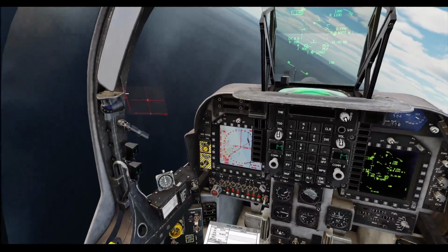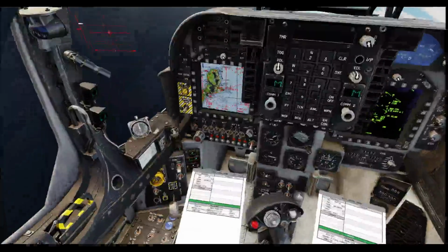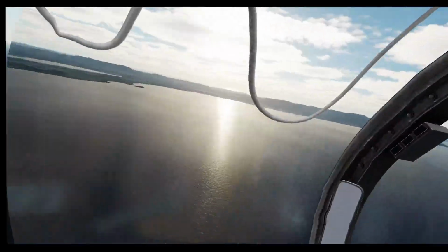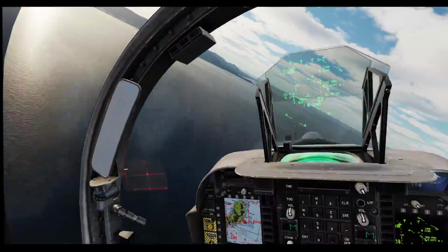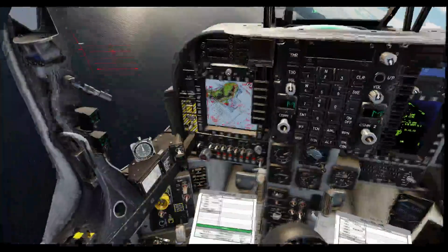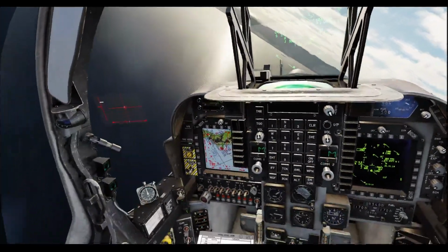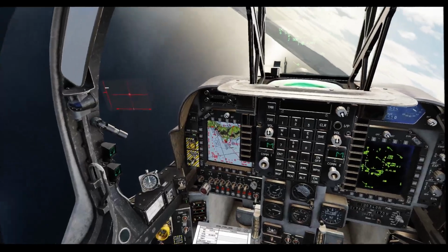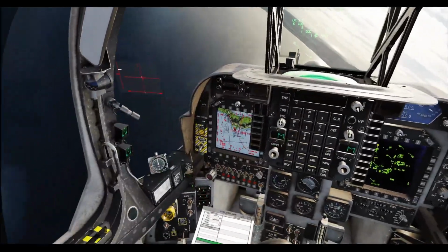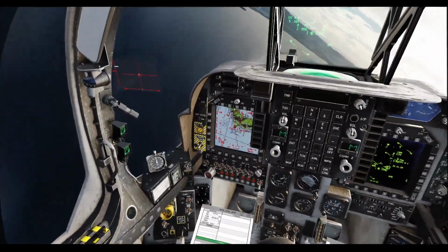And I'm just going to bring the scale out a little bit so that I can see my course line. 0.4, we're halfway through the turn, maintaining that lookout attitude instruments work cycle. So look out the cockpit, reference attitude on the hood, use the instruments to confirm accuracy. So we're at 1.0 miles. 1.2, so we've just got a little bit wide. We want to be between 1.0 and 1.2 nautical miles.